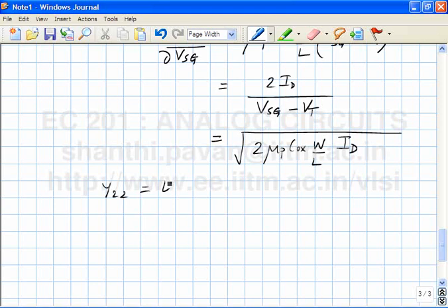In an NMOS transistor, if I increase the VDS, the drain current increases. Even in saturation, where we expected the characteristics to be flat, the current still increases. In a PMOS transistor, when VSD is increased, in other words, when VD goes low, if I yank VD down, the current flowing out of the drain will increase. We added a 1 plus lambda VDS in the NMOS case. So what must we do in the PMOS case?